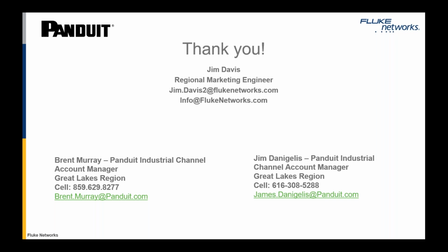Mike mentioned it. I should have brought it up more. The TIA 1152 standard, now in the A revision. That talks about what tests we're going to run in the field, how we're going to run them, and the accuracy. Within the 1152 standard, the values for TCL are specified, but it is not a requirement of the field testing. So yes, the standard specifies what the values are for TCL, but it's not mandatory to run the TCL tests.